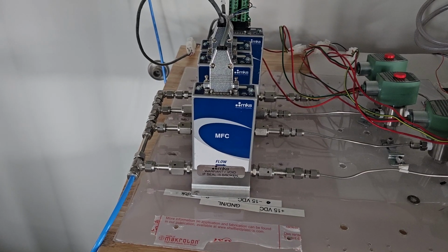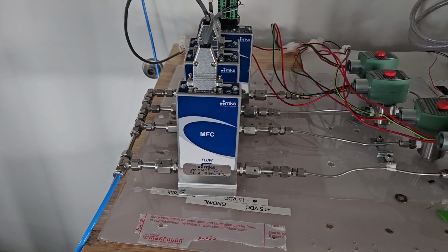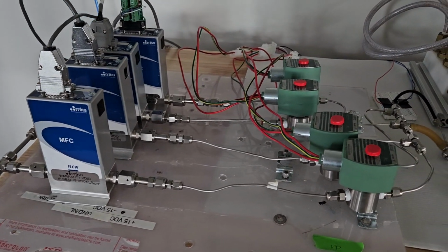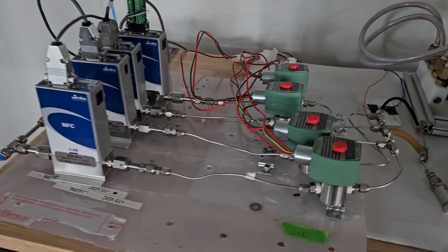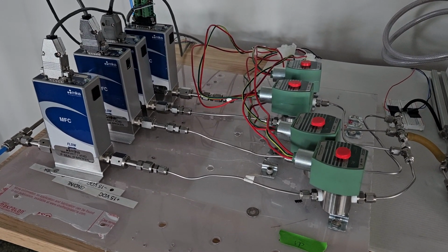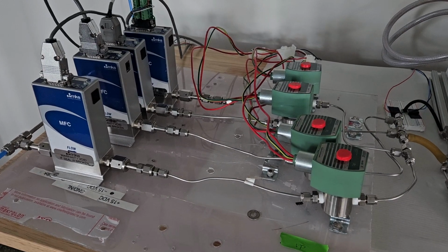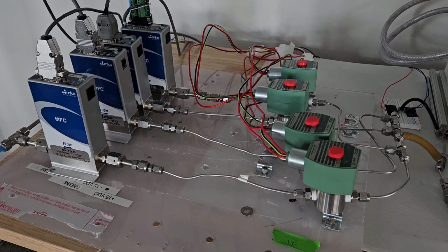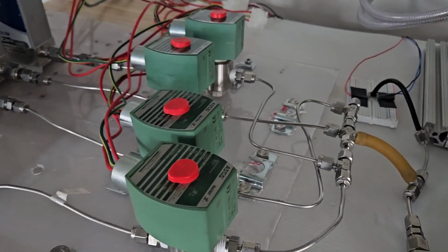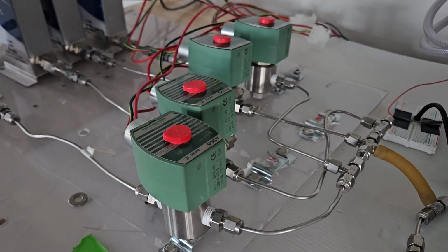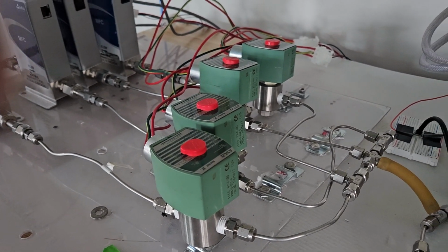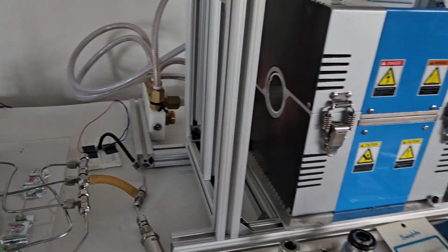The gas flows through the mass flow controller, which only lets the preset amount of each gas through. From there, the gas goes through the solenoid, which can have gas either flow to the room or to the system. The gas that continues through the system then goes to the gas flow combiner. It is here that the 4 separate lines, each capable of running independently and with different gases, combine. The gases mix together into one homogeneous mixture. This mixture would then move into the furnace.